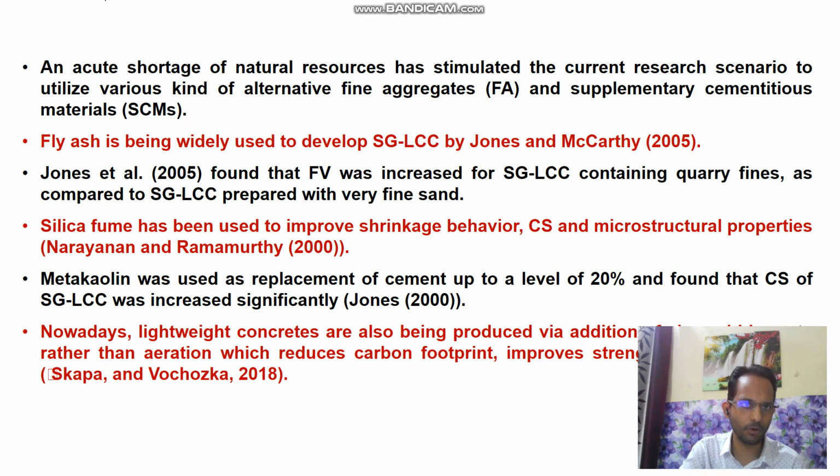As we know, there is an acute shortage of natural resources, which triggered the necessity to use alternative fine aggregates and alternative binders such as SCMs. Fly ash has been used to develop a structural grade LCC. Also, Jones et al. in 2005 found that flow value, or you can say fluidity, was increased for structural grade lightweight concrete containing quarry fines, that is stone fines, when compared to SGLCC prepared with very fine sand.